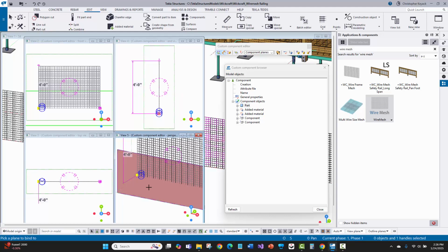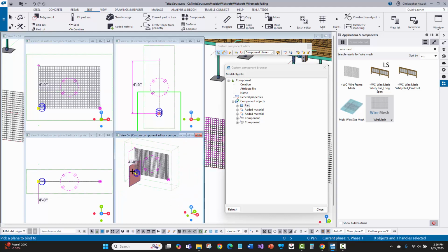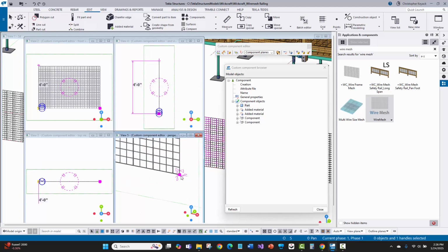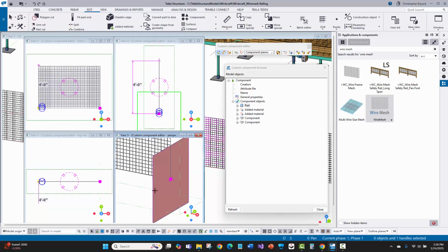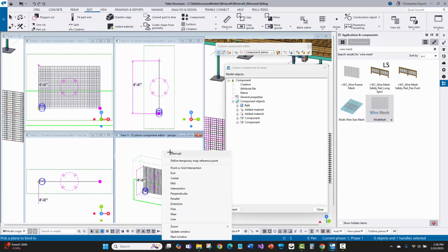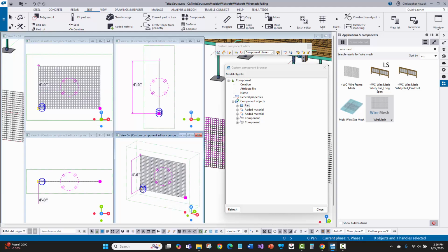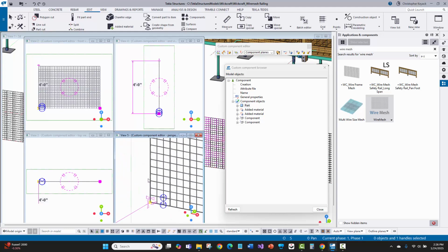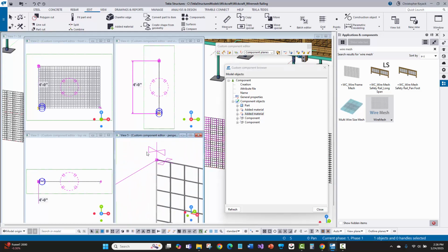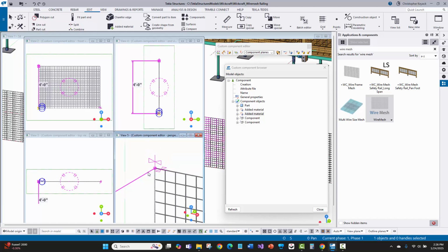So you can see that you can bind it in 3 different directions and essentially glue the start point of that beam to the first point picked. And then the second point can be bound to the second point picked. There's that end plane there, right? For the second point for the component. So I bound that so that source bar is always going to be there. And then I also modeled in a vertical bar here, and I did the same thing. You'll see that the start and end points are also bound to those planes.